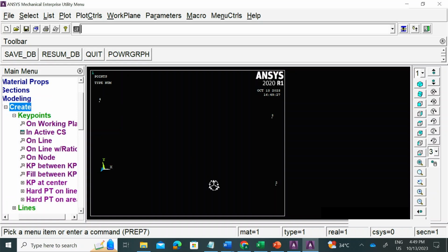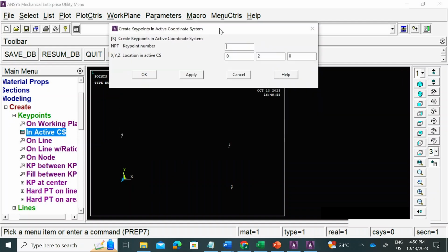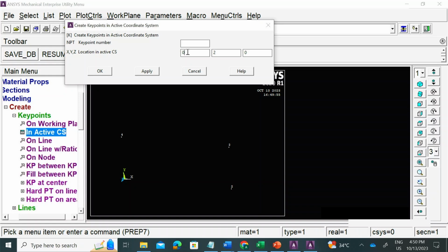I want to now create a few lines, but I want to create a few more points so that I can make a cuboid or something like that, right? So let me create a few more points. In place of this, I had this 0 0 0 as the first point. So rather than 0 0 0, I want to go to negative z, so negative z of -2. Z is pointing outside the screen, so I want to go inside the screen, right? If I do apply, it creates the point 5. So the previous point 5 is gone, so this is the new point 5.